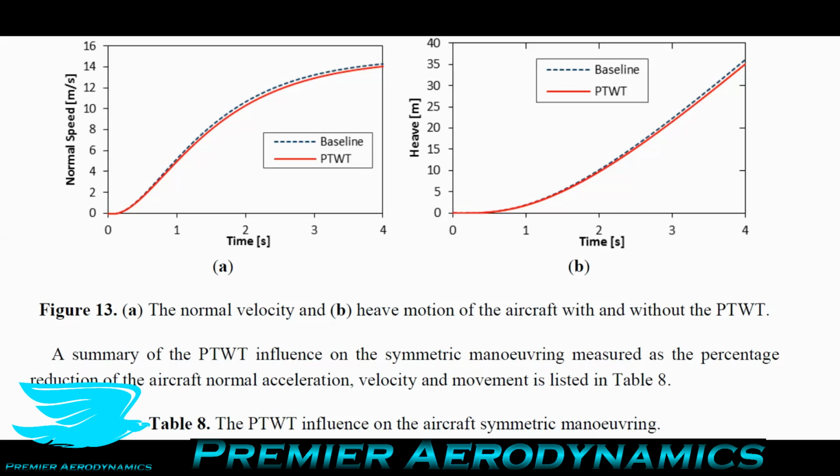The reason why these three parameters are very important for your experiments is that they affect the density of the air that you're using. This density then will affect the velocity that you're calculating. It will affect the non-dimensional coefficients, such as the drag coefficient and lift coefficient. It will affect the Reynolds number, and so on. So if you don't accurately measure the density, you're getting errors in these values. And the worst time is when you don't even know that you have these errors. Then when you try to validate any CFD that you might do, your density is going to be different, so your drag, your lift, and all that are going to not line up. That's going to give you headaches.